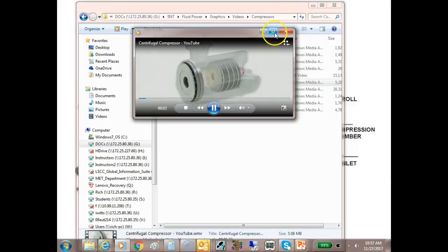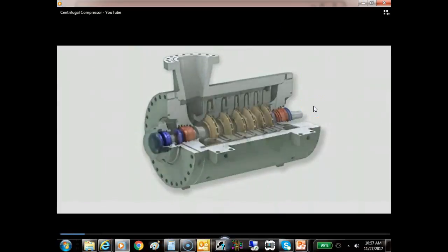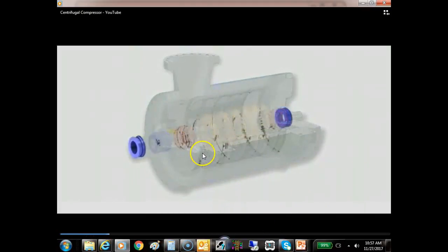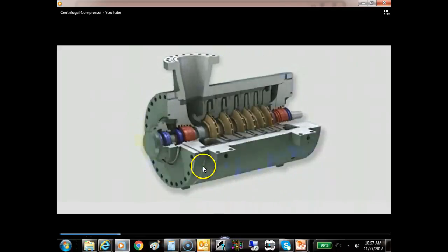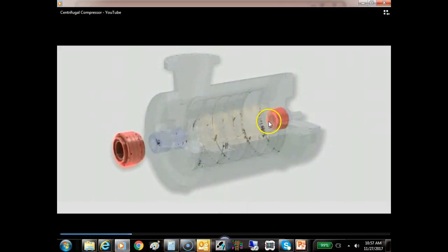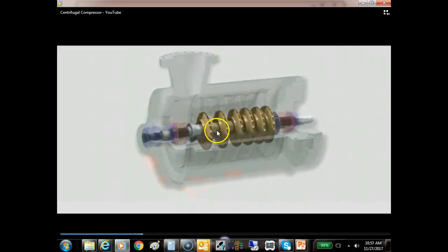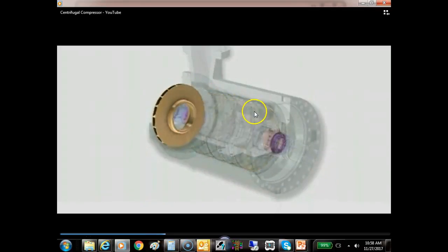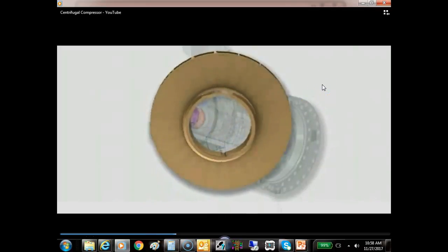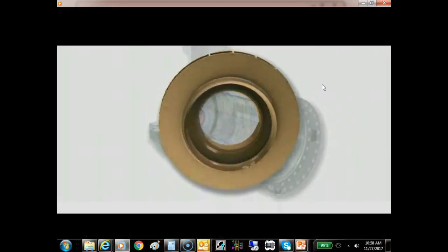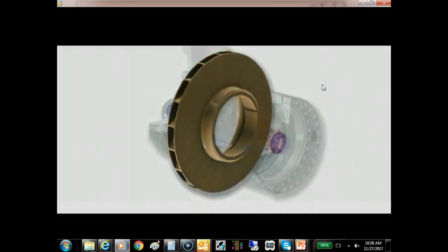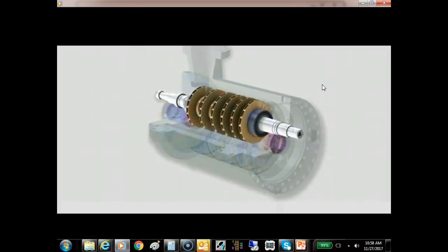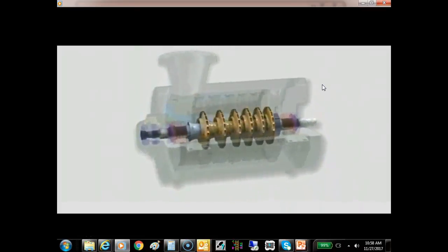This is a centrifugal compressor. And you can see this guy's got how many stages when it pops back in there? 1, 2, 3, 4, 5. It looks like it's got 6 stages of compression. So basically, you've got one that feeds the other, which feeds the other, which feeds the other, right? And basically, what does it do? It sucks the air in on the center, and then when it's spinning, what happens? It just pushes it out. And if we change the volume when it starts going out, then it's going to pressurize it, right?